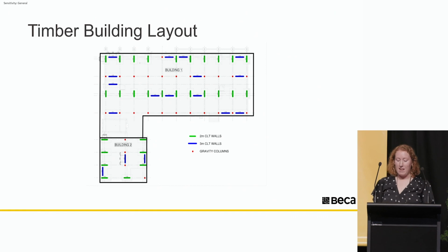Overall, looking back, I think we should have pushed for more size in our vertical structure, wall length and column size. We thought we were generous with the sizes, but in reality, the sizing was just enough and led to more complex connections. Don't underestimate timber sizing required to make connections work.